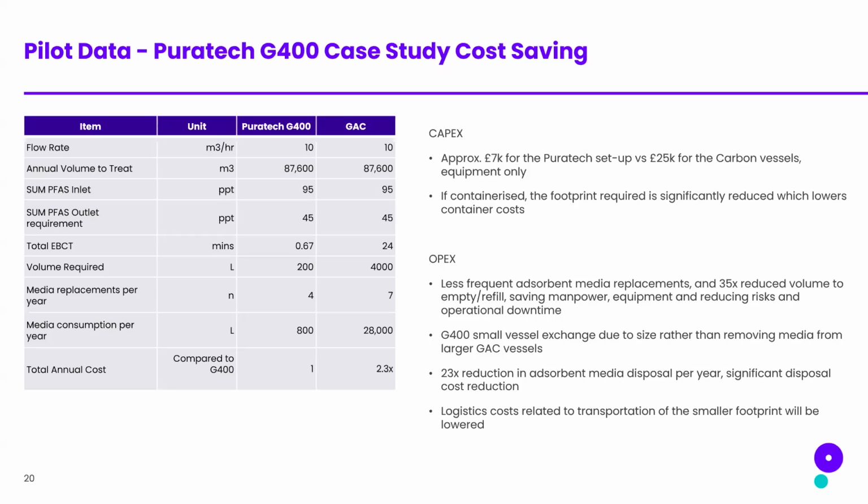It's a lot smaller footprint, and rather than having a truck go out there where you have to pressurize the vessel, slurry the material in and out, here you unscrew the top, unscrew the bottom of the inlet and outlet piping, put a new tank in, hook it back up, and you're gone. So basically, the change out of the equipment can be done in under an hour, probably under 15 minutes, depending on how many vessels you're changing out, compared to typically a day-long process if you're changing out a large carbon unit.